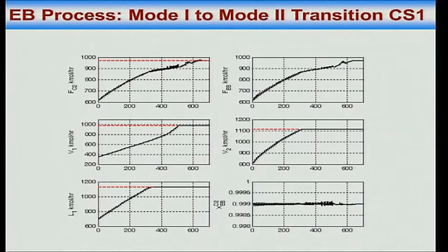Then I think last but not least, you keep changing the set point. You want to increase the throughput, so what we are doing is we are increasing the V1 set point by 10%, okay, and taking it to max. And what you find is that the FC2 keeps increasing. The rate of increase changes because constraints are becoming active. So L1 becomes active somewhere here, somewhere here L2 becomes active, V2 becomes active, and finally V1 becomes active someplace here.